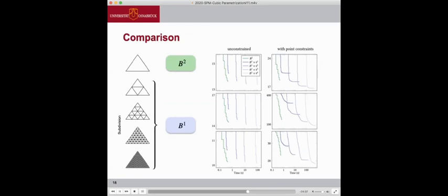It can be observed that with an increasing number of linear pieces per element, the final distortion decreases. But to achieve a distortion as low as the quadratic case, 16 to 64 linear pieces per element are necessary, and with those, the optimization takes quite a bit longer than for our higher order setting.